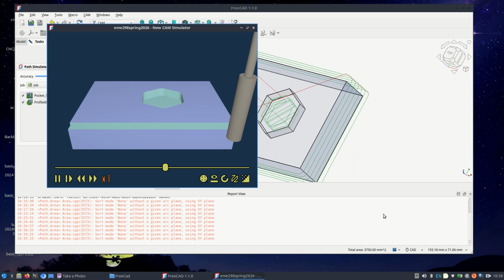Why did it cut the first pass and still mark it as cutting something? It's because I added 3, but the first pass it does actually goes down 3, so it was right on the surface. I thought we had it +3, so it would be above. Maybe the software doesn't bother to check if it's actually touching the part, it just draws it as blue. No, it doesn't mathematically check if it's touching the part.